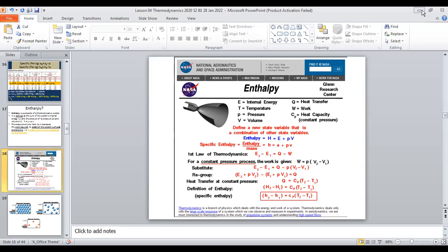Energy balance. So U is the primary energy content in this working flow. But the flow work is also involved here, because by having PV, this has a higher energy level, additional energizing to push through this. So H2 is something like a total energy, including the energy because of the flow work, because this energy is needed to push this in and push this out. So the additional energy needed for the flow work is also included here. That's why we have H1 and H2.